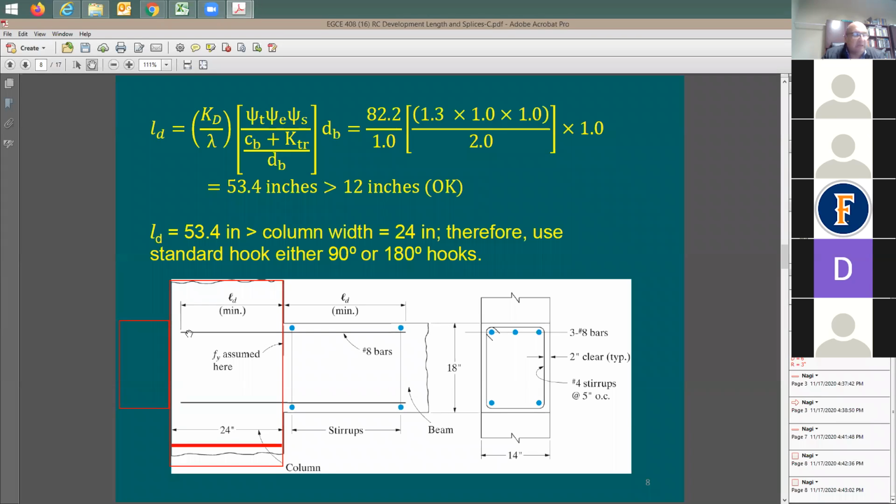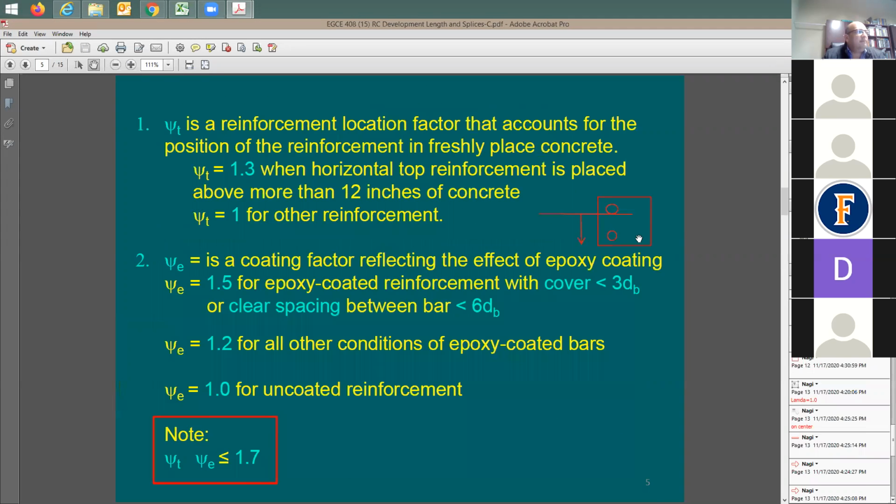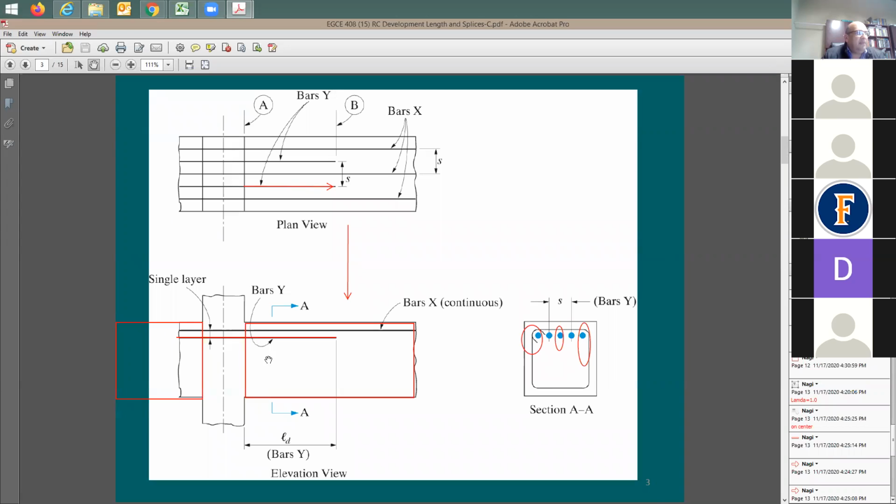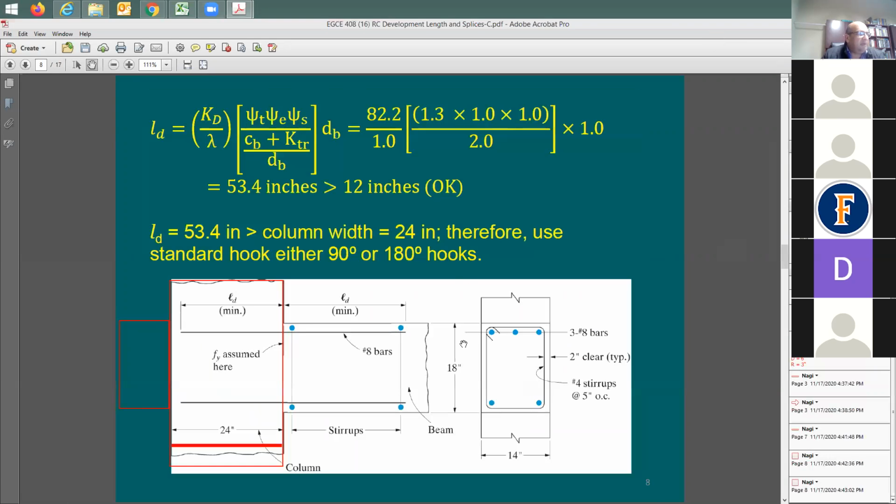It is true that if you're going to an example like this, and you have an extended beam, it's just going to be easier if you throw the bar there. But in this case, because this is going to be a column at the end of the beam, you're going to be in trouble, and then you need to do an extension of the beam like this. It's going to be sticking out of your building, and that doesn't make any sense.